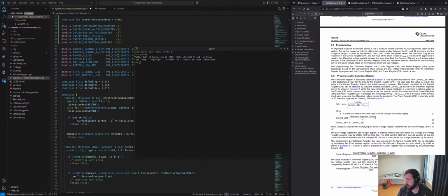Okay, so maximum expected current on this. We're going to switch to a Raspberry Pi 5 at some point. I'm going to say the regulator in here has a continuous supply rating of 7 amps. It can spike up to 13 amps without failing, but it can't supply 13 amps continuously.